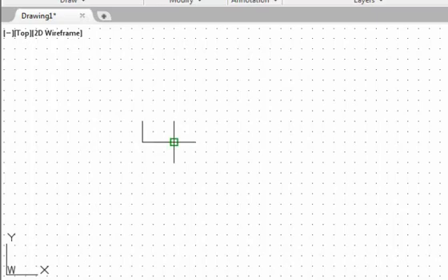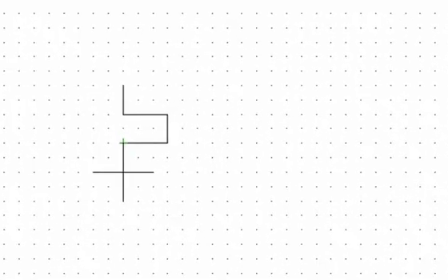Next line is 0.5 inches below the last point. For small distances, by setting up the snap increments correctly, this actually helps us to create this design very quickly. For the next line, I need a horizontal line that lines up with the first line segment. Click once with the left mouse button and create the line. Then I want to go down 0.25 inches.